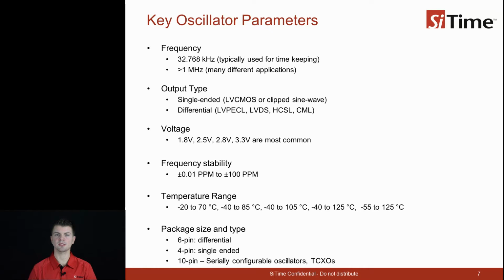The power supply voltage, most often denoted as VDD or VCC, is the third most important characteristic. Some oscillators are designed to operate over a wide range of VDD, such as 1.8 volts to 3.3 volts nominal, while others are designed to operate at a specific VDD, such as 3.3 volts. For best performance, filter circuits are often used on the oscillator voltage supply rail and can range in complexity from a single decoupling capacitor for low power oscillators to an RLC network for a high power differential oscillator.